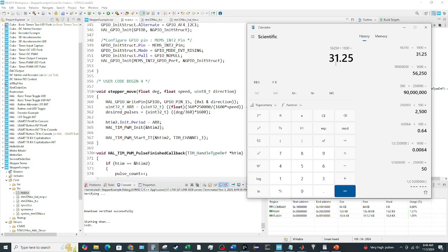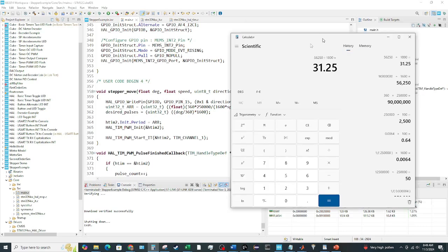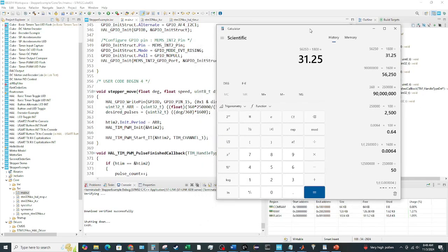So you can see we had our pulse set to 499. So this obviously wouldn't work. You try to move fast, you're not going to have a pulse because your pulse is longer than your period. So we actually need to put a pulse value. If this is the max speed we want to move, the pulse is going to need to be less than this. So let's change our pulse to 9 so that we'll have a pulse width of 10 counts.